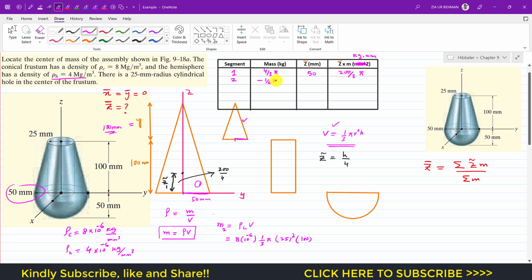And now the location of its centroid from the y-axis. Its centroid will be located somewhere here, and again from that table, this distance will be h divided by 4. Its height is 100, and 100 divided by 4 will give us 25. But this cone is at a distance of 100 from the y-axis, so 100 plus 25, that is 125.